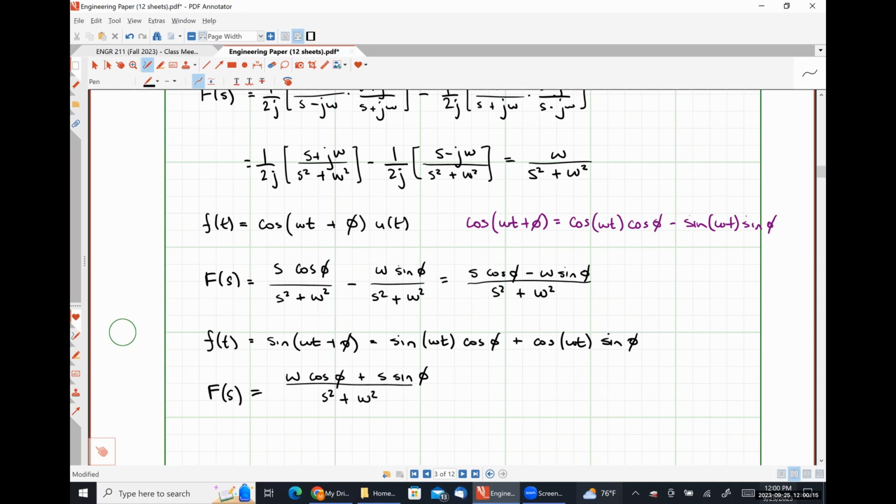I say that as if it's simple, and then you guys caught me making a mistake on that very thing in the homework solutions. Couldn't do them as late at night as I was doing this. Referring voltages, V2 over V1 is equal to either A or negative A, depending on whether the dot's on the same side or the opposite side. Current relationships follow a similar thing. Why do you need an equation? You don't. So you don't get one.